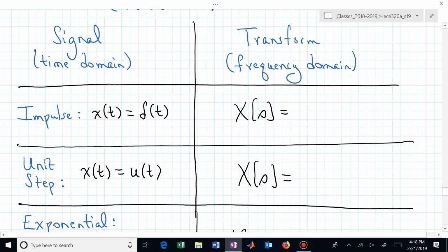The impulse. In the time domain, that's the impulse. That's what the impulse is, right? It's an infinitely tall, infinitesimally wide waveform, and you excite your system with that impulse. Another way of thinking of that is that impulse initializes your energy storage elements, and then it's gone, and you basically have an initial condition response.